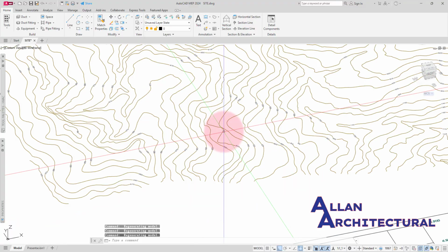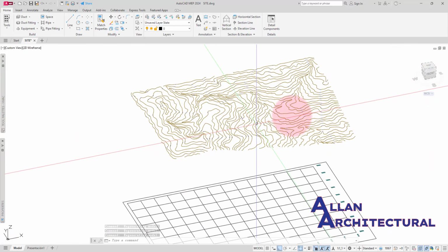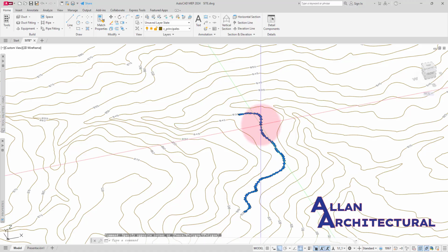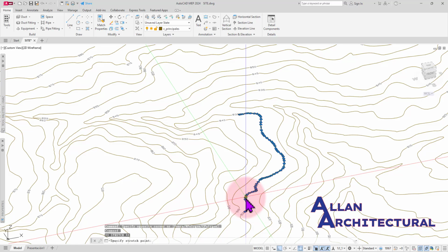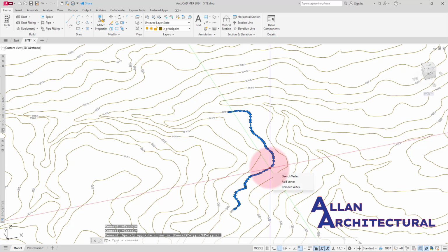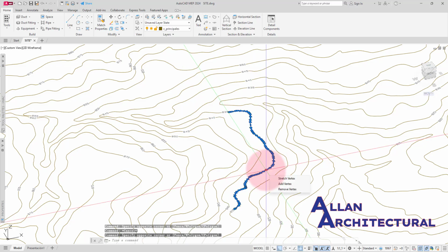Now one thing we can actually do is get the coordinates at which all of these heights actually move in there. All right, so I'm going to select any of those contour lines in there, and I'm going to type LIST on the keyboard. Now just make sure you hit LIST on your keyboard and just enter that in there. Okay, let me just get out of there and select it back, and let's just make sure we select this and type L.